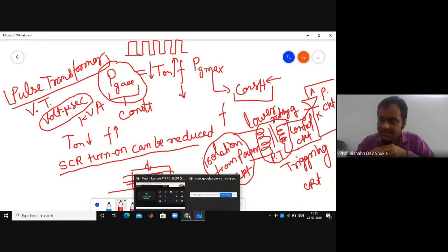For an SCR, the gate cathode characteristics has a straight line slope of 130 ohm. For a triggering source voltage of 15 volt and allowable gate power dissipation of 0.5 watt, compute the gate source resistance.